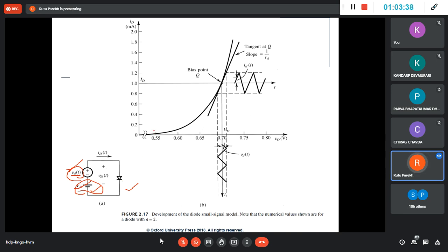So this millivolt falls here somewhere. Here, the diode is always dead. If this voltage is small, it stays dead, but if this voltage is big enough, then okay, you don't need the bias. If I'm talking of 200 volts, let's say, then 0.7 is always on. 200 volts minus 0.7, even with that little voltage drop, is still 199 point something. So it is not necessary to have this bias voltage.